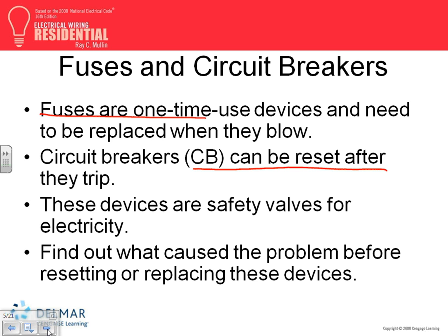But the good thing about fuses is they size them specifically for the load. The fuse manufacturers can tell you, I guarantee you, if you have a short circuit, this piece of equipment will not burn after it clears the short circuit. The circuit breaker doesn't have this type of guarantee. The circuit breaker guarantees that if you have a short circuit, we will interrupt it. But after we interrupt, what happened to the cable? Is the cable damaged? How much damage happened to the cable, the circuit breaker, the transformer? The circuit breaker doesn't guarantee that. That's kind of the disadvantage of circuit breakers.